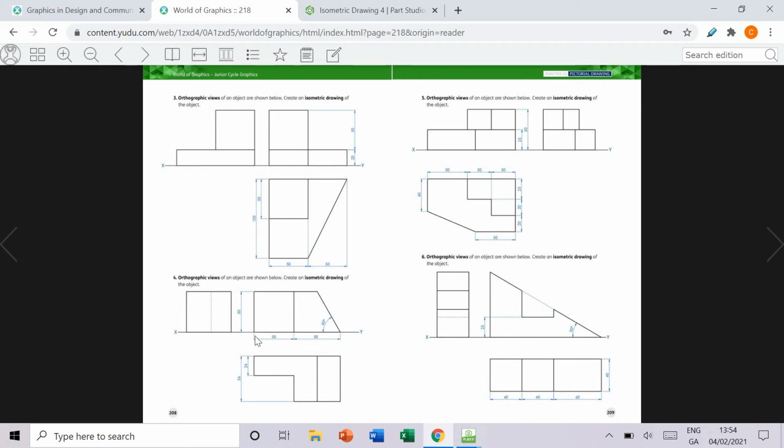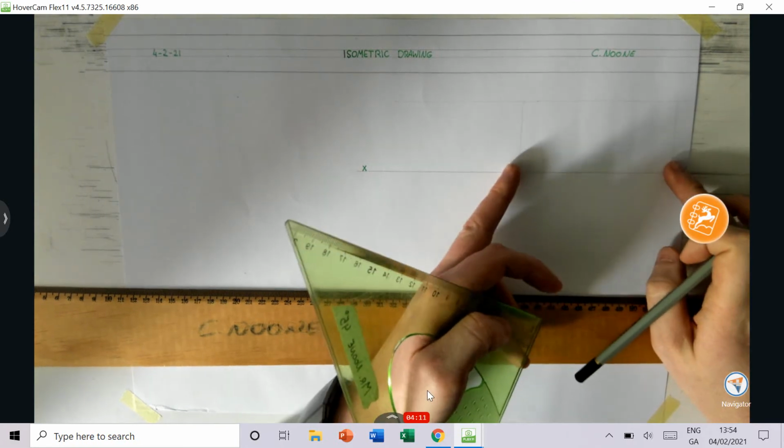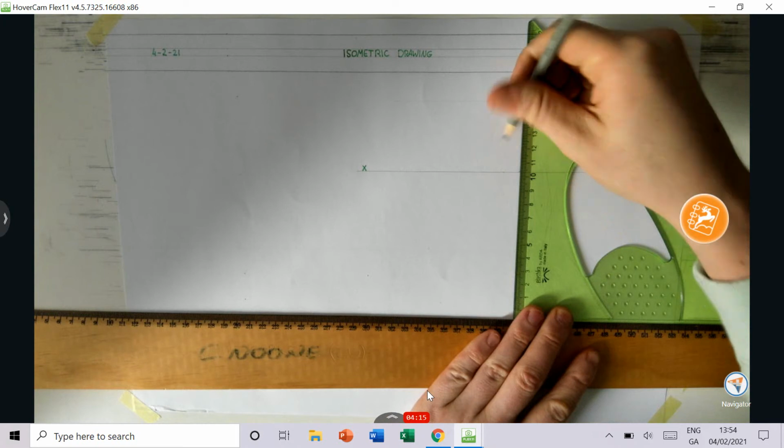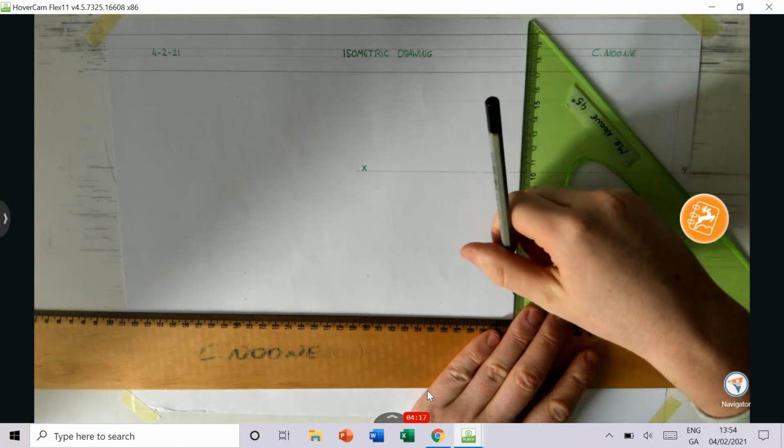Okay, so exactly below that shape, so I'm going to drop this line down, I can start drawing my plan. And I know that the depth of that shape is going to be 56. Okay, 56, and the width doesn't change, so it's going to be 108 wide as well. Okay, so this is for the plan. So the width doesn't change, so I'm going to drop the width straight down. Okay, two construction lines, just dropping that width straight down.